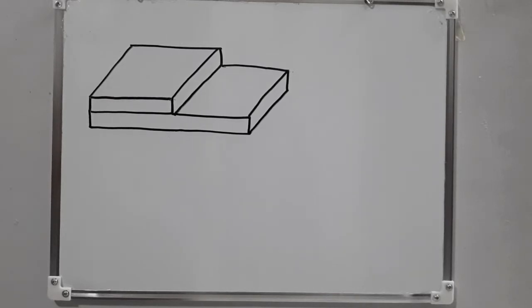There are different types of welded connection, but for today, we will just discuss your fillet welds. This is the most common weld that we are using in the industry. Fillet welded joints such as T, lap, and corner joints are the most common connections in welded fabrication. Fillet welds join two overlapping pieces or two pieces placed perpendicular to each other. For example, this is our figure.